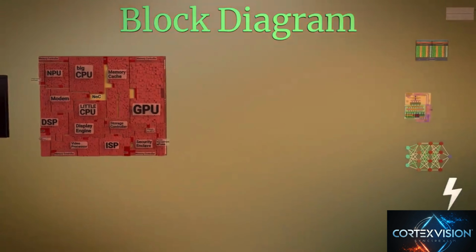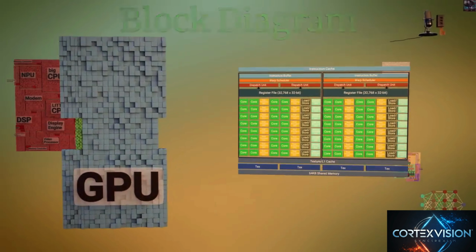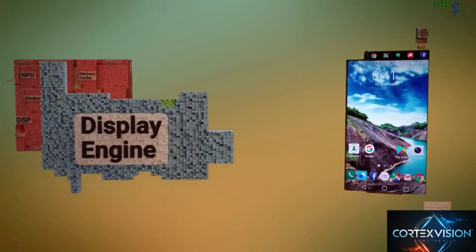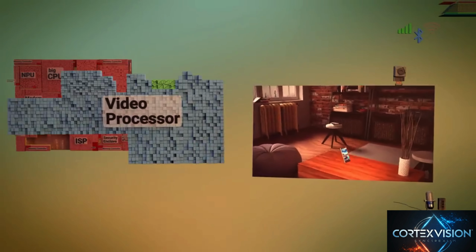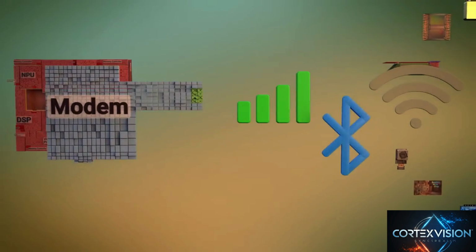The key areas in the SoC are the CPU containing multiple cores, the GPU which renders graphics, the shared memory cache which is usually around 4 to 8 megabytes, the digital signal processor which interfaces with things like the speakers, microphones, sensors, and many other things, the display engine which communicates with the touchscreen display, the video processor which compresses and decompresses images and video and enables 4K video recording and playback, the image signal processor which processes pictures and video taken by the cameras, the modem which interfaces with the various wireless networks, the storage controller which saves and